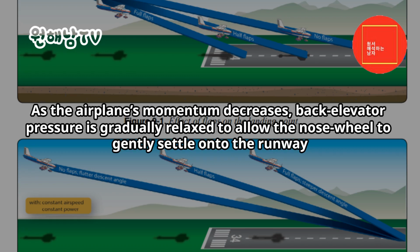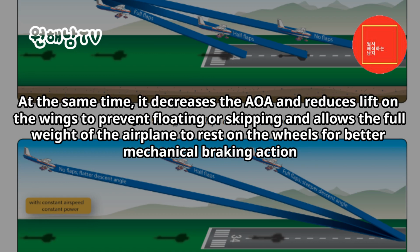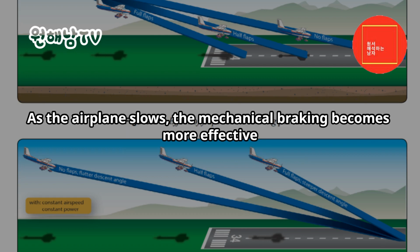As the airplane's momentum decreases, back elevator pressure is gradually relaxed to allow the nose wheel to gently settle onto the runway. This permits steering if the airplane has a steerable nose wheel. At the same time, it decreases the AOA and reduces lift on the wings to prevent floating or skipping, and allows the full weight of the airplane to rest on the wheels for better mechanical braking action. As the airplane slows, the mechanical braking becomes more effective.